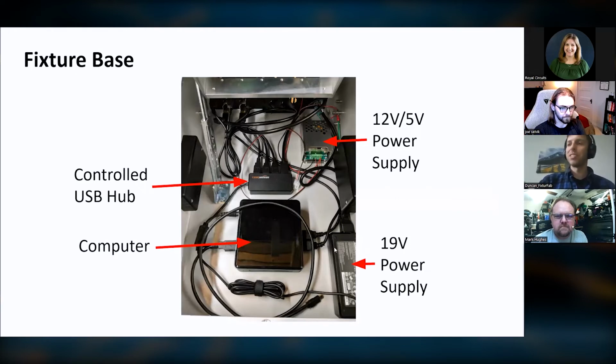Any of the power supplies that are needed to power the device under test, or the various instrumentation, and a USB hub as well. And the cool thing about this is you can show up to the manufacturer, you just have a big box that you put on the workbench, and then you just hook up a couple of things over USB and an HDMI cord to the monitor. You have a functioning test system. You don't have to wheel around an equipment rack and deal with hooking up all that stuff.